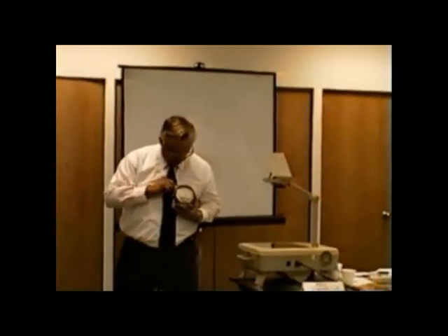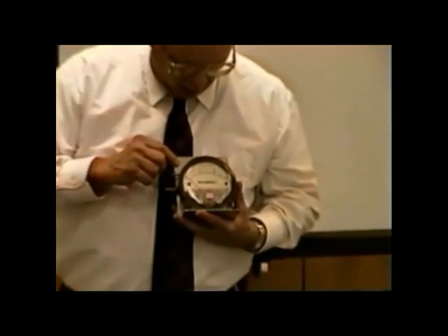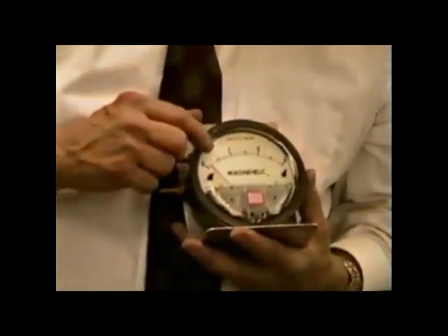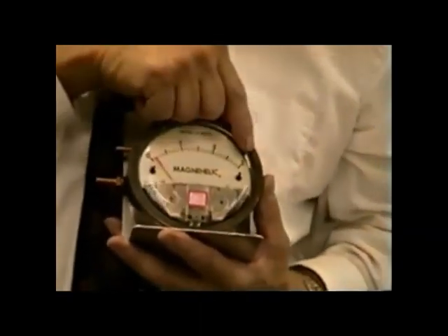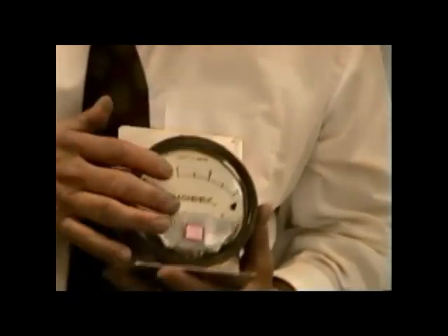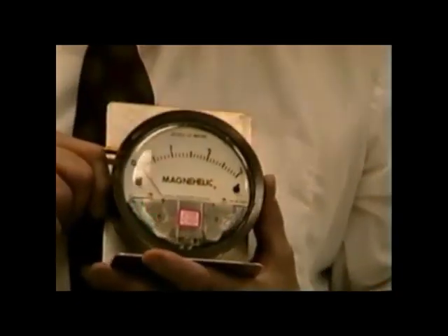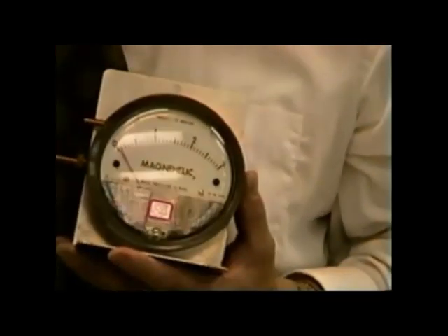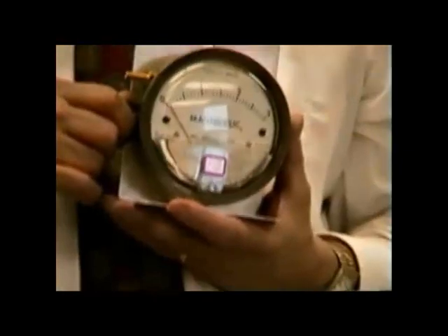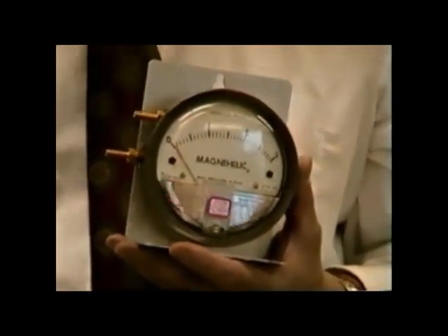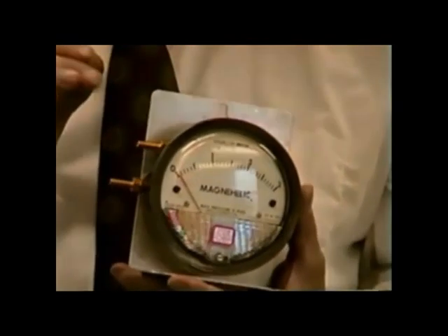We use this for pressure switches and other things. But we can have magnehelic gauges that go from 0 to 15 inches, which is nice for checking furnaces. We can also go from 0 to 30 inches. This is a Dwyer magnehelic. It's very sensitive, very accurate. Sometimes technicians have the little small gauges. I think Richie makes some of those, and those are fine, but they go from 0 to 35, and they're harder to read, but they're fine. Again, it depends on what you're used to.